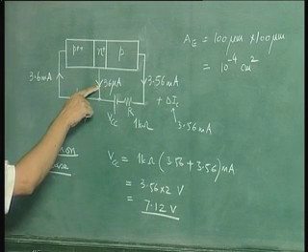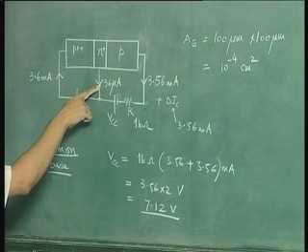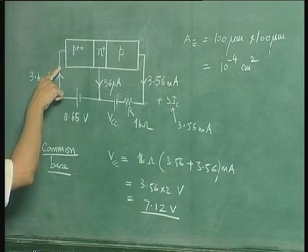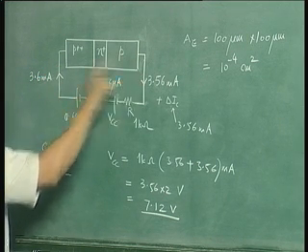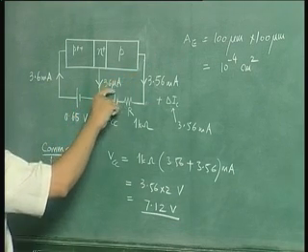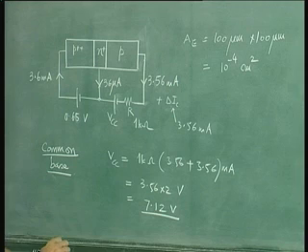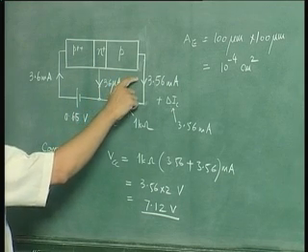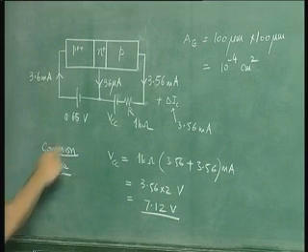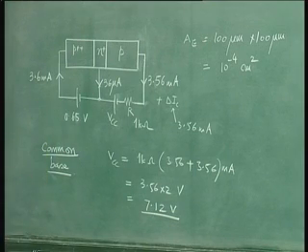If we use the base lead as the input terminal instead of the emitter lead, and continue to use the collector as the output terminal, then clearly from base to collector there is a factor of beta increase in the current. So we will be able to get the current gain also in addition to the voltage gain. So the configuration for common emitter would be as follows.